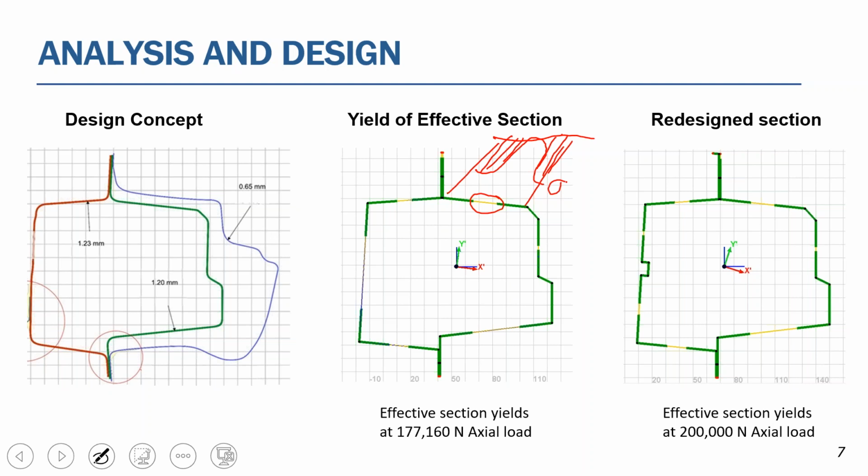So the yield stress would be at the corner and would have a much lower stress here in the area where we've thrown away the material. So we're saying that in this condition, all the corners are at yield in this section because it's under an axial load, and something less than that everywhere else.